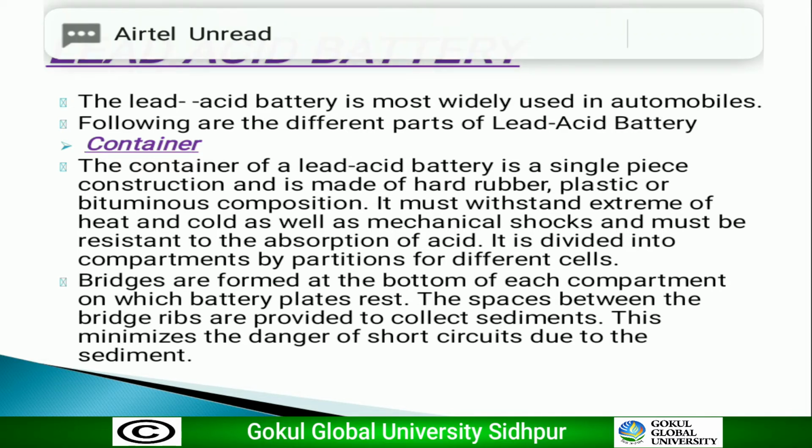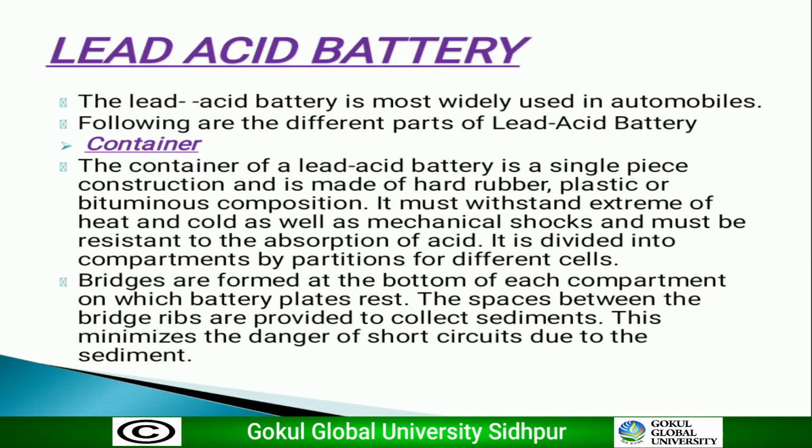This container holds the battery plates and electrolyte in it. Why hard rubber? Because the electrolyte is a highly active material, so we need hard rubber, plastic or bituminous composition. It must withstand extremes of heat and cold as well as mechanical shock.